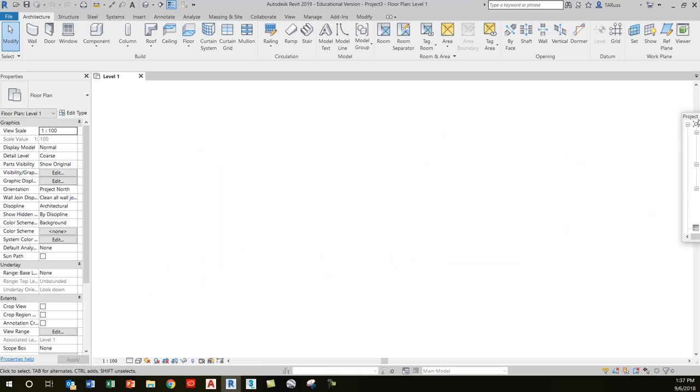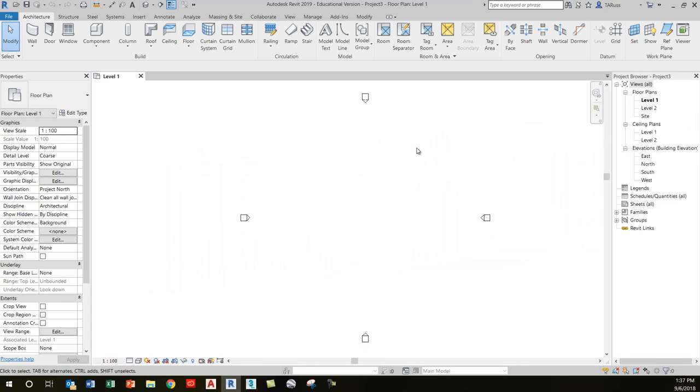Now, this is admittedly a personal preference thing. In the early stages of a project, it doesn't really matter that this is separate from this, but eventually we're going to have a project that has all sorts of additional views in it, additional floor plan views and sections and details and all the rest, 3D views. So it starts to get to be a long list, and it'll be a little bit inconvenient to have it located underneath Properties where you need to constantly be scrolling to access the view names. But again, that's personal preference. You might be fine with just leaving it underneath the Properties window.